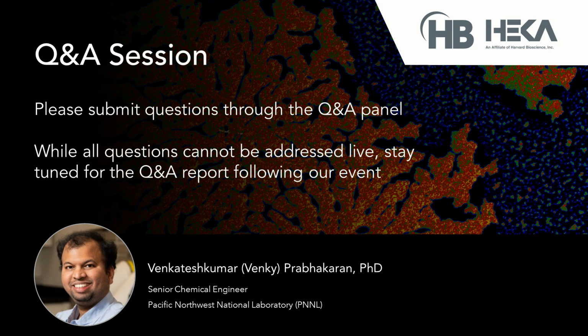Again, we believe that is probably still to do with the micro humidity changes going on around the tip, because the impedance is very sensitive to that part of it. For example, any micro precipitation that forms around the tip could affect the impedance response. So that's one of the challenges we are still facing: to stabilize the tip and control precipitate formation at the tip, especially when you use the salt solution. So I think that's one of the reasons it's not well correlated with the microstructures.